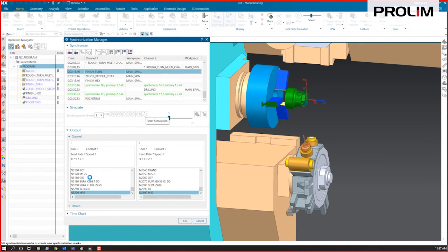We'll reset that machine to regenerate the code. You can see the sync marks. It'll regenerate those and put those in the right places in those new ones that we added. So it's going to run this actual NC code through this simulation process.